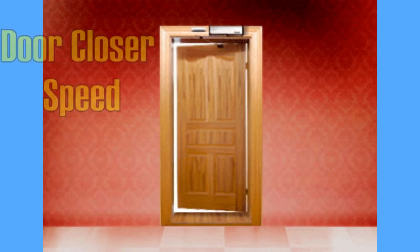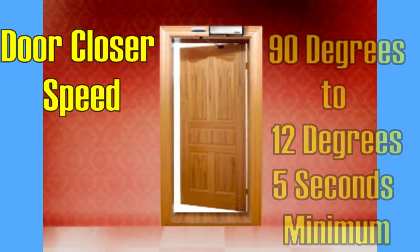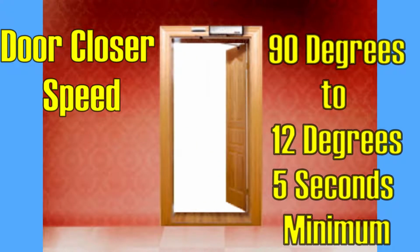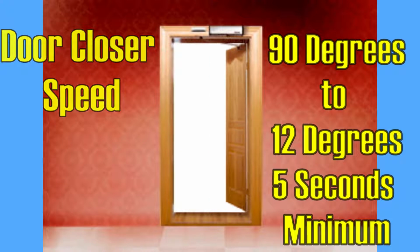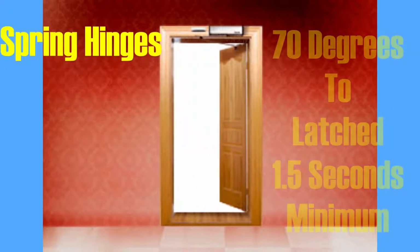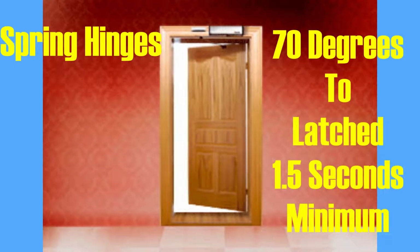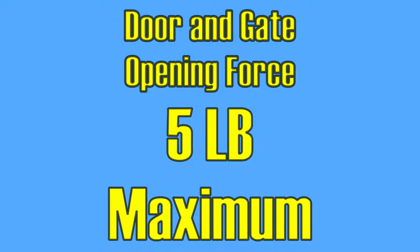Door and gate closers shall be adjusted so that from an open position of 90 degrees, the time required to move the door to a position of 12 degrees from the latch is 5 seconds minimum. Spring hinges from an open position of 70 degrees to latched in 1.5 seconds minimum. The force required for pushing or pulling open a door or gate, other than fire doors, shall be 5 pounds, including sliding doors.